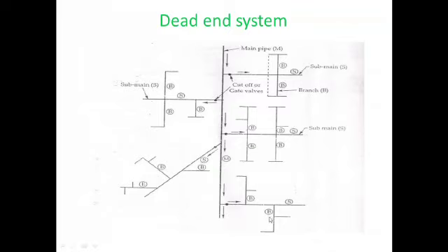And there are numerous dead ends in this system which prevent the free circulation of water, and there may be stagnation of water, which may lead to the degradation in its quality, and this stale water should therefore be removed periodically at all the dead ends by providing scour valves at each dead end, which will result in greater wastage of treated water and will necessitate careful attendance at each valve.